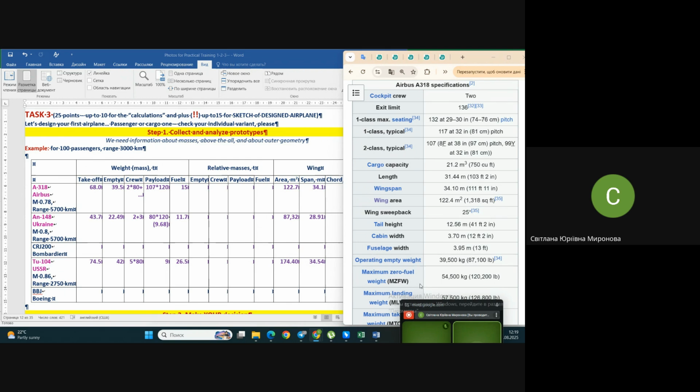already not by approximate formulas, but next understanding approximately the geometrical sizes of airplane, you will be able to determine approximately the loads acting on the airplane, air loads, weight, and so on. On the next stage, when you already understand the loads, you are able to calculate the inner structure.